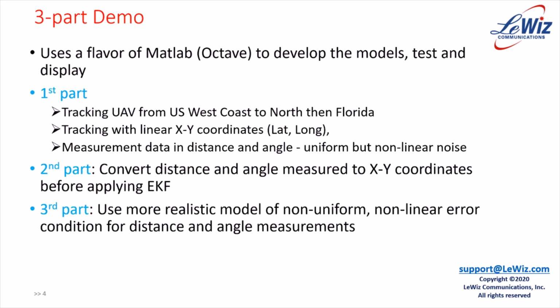And then the second part, instead of using distance and angle, we will convert that into XY coordinates before applying the extended Kalman filter. Here, we're talking about XY coordinates, but in terms of longitude and latitude, we need to take into account the curvature of the Earth, and the model that we develop and the data do take care of that.